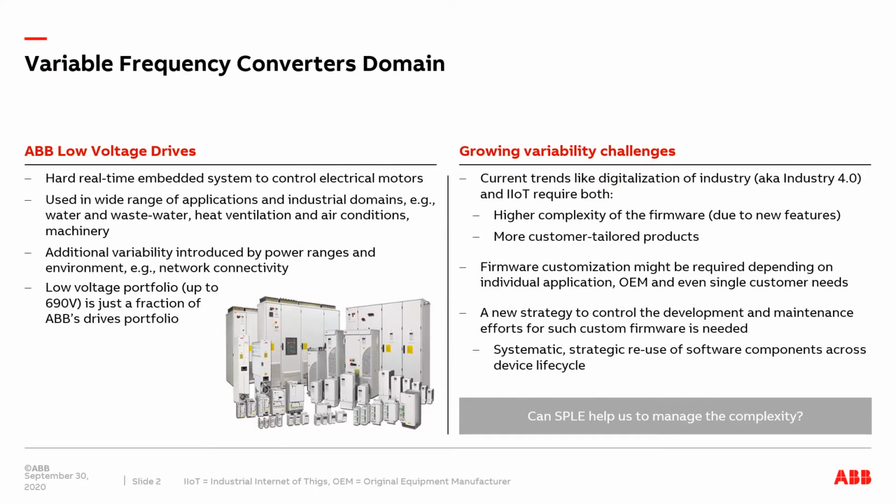Before we start, let me spend a minute on explaining our application domain. In this paper, we work with the domain of low voltage frequency converters, or so-called drives. This is an embedded device which controls electric current and voltage to speed up and control an electrical motor application. Typically you're interested in controlling rotation speed or torque, and you can use these devices throughout the industry, for instance, in applications in water and wastewater treatment, or in air conditioning systems, or in machinery